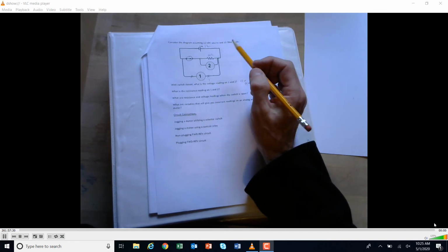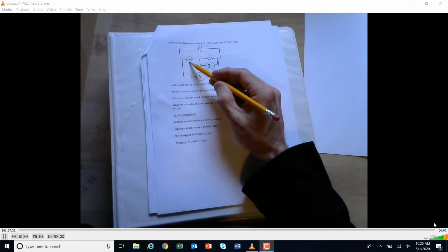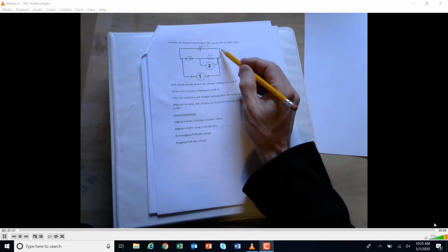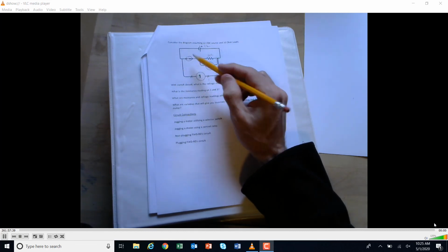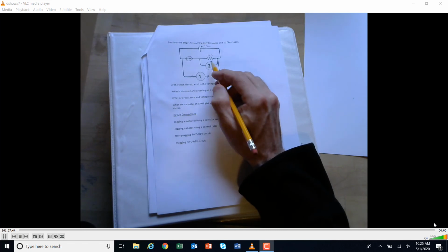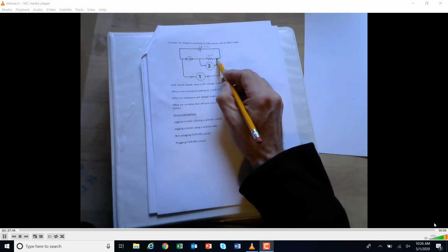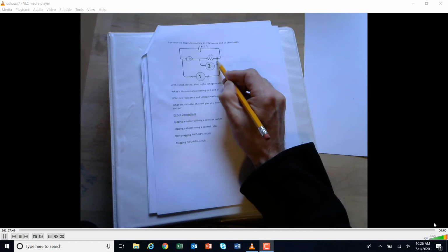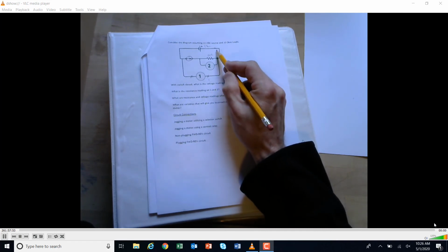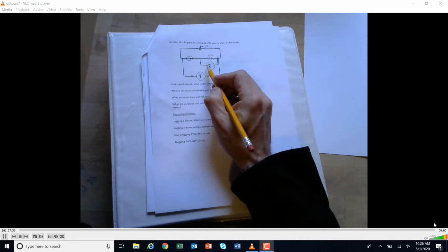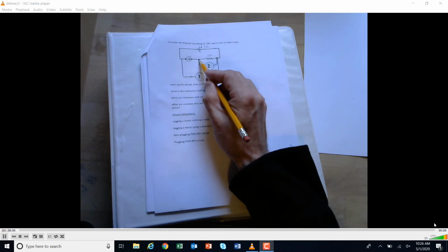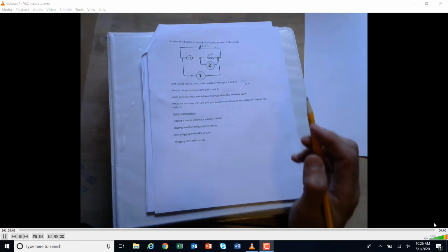Measuring resistance, well, if I look at 1, if this was open, it looks like I'm measuring the resistance of the battery. So that's not good as a voltage source. Who knows what we're going to get. When this is open, number 2, well, I'm on this side of the load and this side of the battery, so I could possibly be doing either or. But on this side, this is open, so I'm really only measuring this, and I would get 10 ohms.